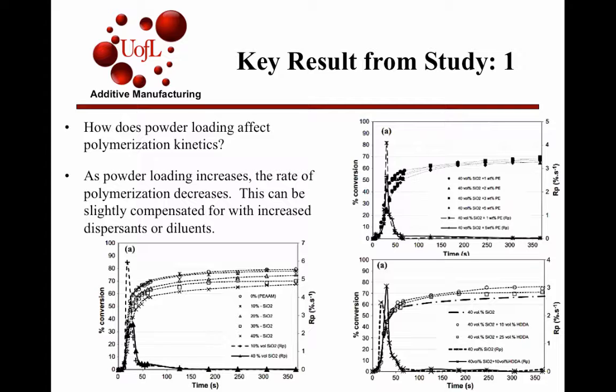And then they also tried changing a dilutant material in there, adding that, and that actually had a bit more of an effect than anything else so far. And you can see that with 0% dilutant, it's a pretty low value, and then it shoots up at 10% and then drops back down. So there's a value somewhere in there that's ideal for diluting that amount of silica.